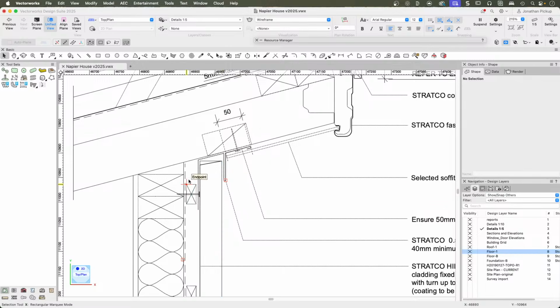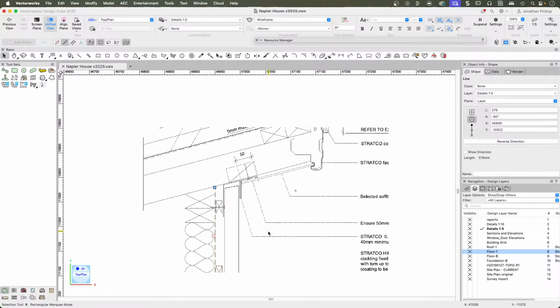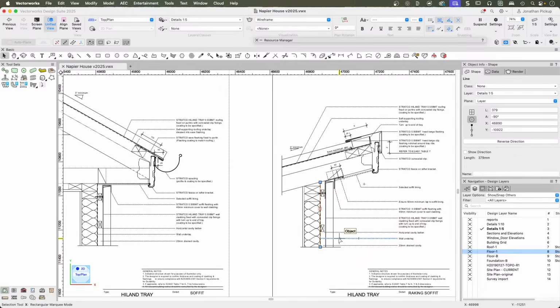They say, okay, well, this is a rain screen. I know water's going to get through, and this is my building wrap here. So that's my next level of protection. We make sure that any water doesn't get through that, and then that will drain the cavity. So the water might get in, but we'll drain it. As I said, bricks are the drying, and the last one is durability.